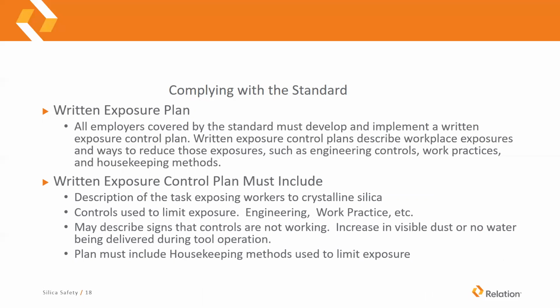So the plan must include the description of the task exposing workers to crystalline silica, and the controls used to limit the exposure. It may describe signs that controls are not working, such as an increase in visible dust or no water being delivered during the tool operation. So these are hazards that could come up. And the plan must include the housekeeping method used to limit the exposure.